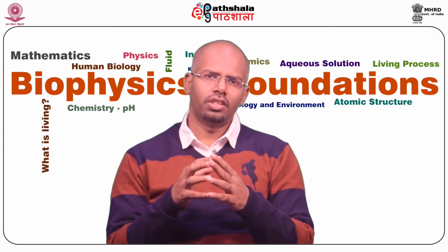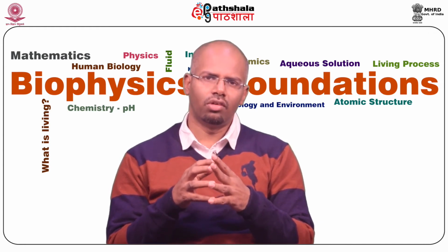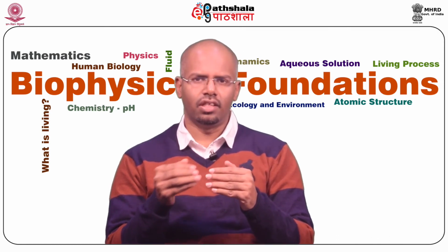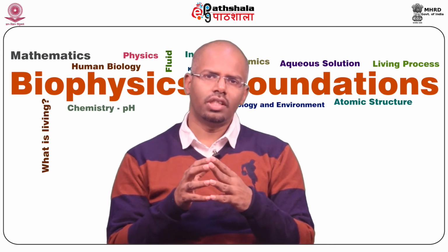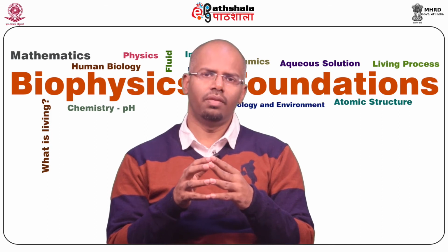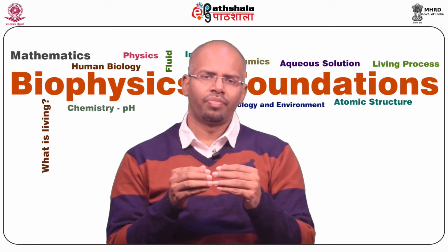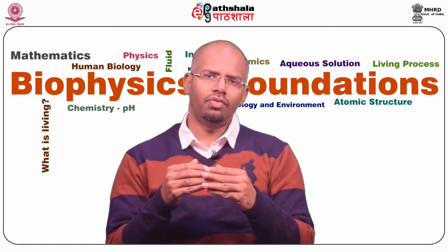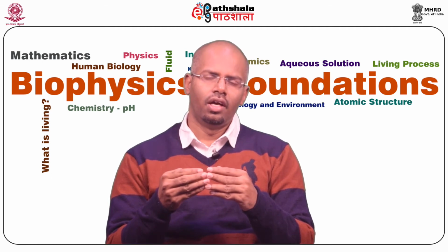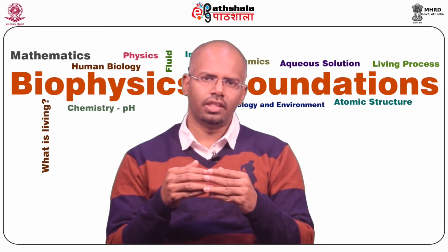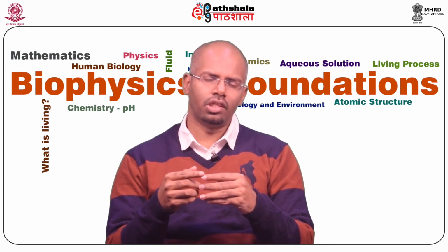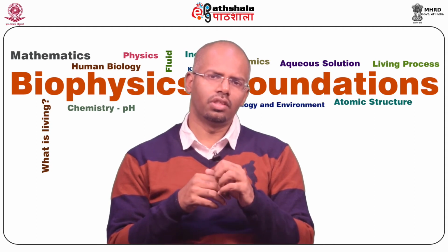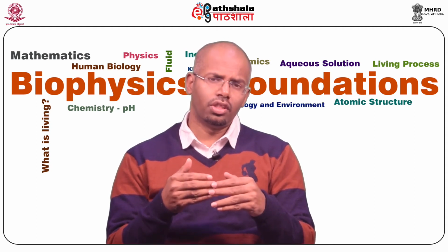The voltage across the resistor is regarded as a real quantity, which means the voltage is in phase with the current, while the voltage across an inductor is regarded as a positive imaginary quantity, which means when there is an inductor coil, the voltage is going to be shifted in time ahead of the current, and that is what is called a positive imaginary quantity. And then for the voltage across a capacitor, we have a negative imaginary quantity. Negative meaning the voltage is going to lag the current